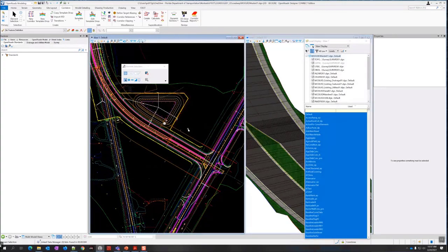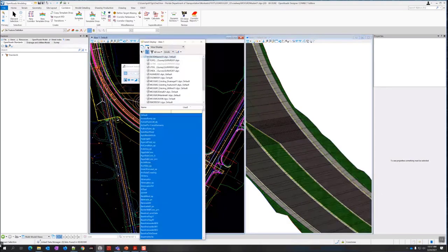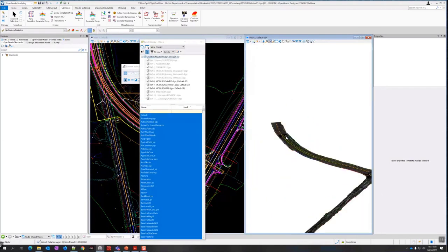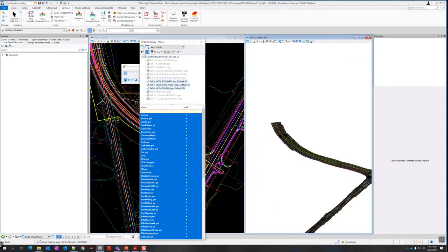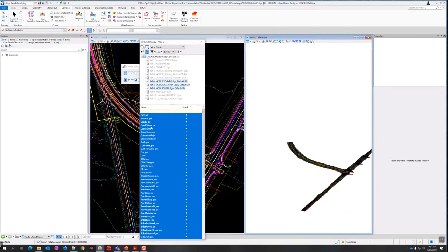Let's see here. So let's go ahead and turn off the levels that we need. I've got my 3D view open. Let's make my 3D view active. We're doing this from the 3D view again. I still have these three files displaying. That's all I need. This is proposed again, so make sure these others are off. That's good to go. So select these three. Hold down Shift and select all of them. And we're going to turn off...